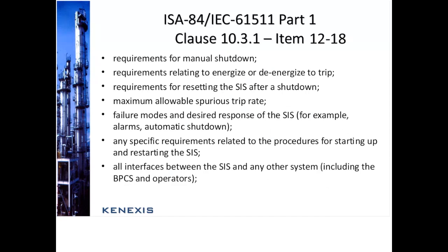Requirements for manual shutdown. Things like NFPA will require that even if you have a logic solver, sensors, and final elements, your valves, there needs to be a manual means by which a person can intervene and cause everything to go to the safe state without the use of the safety instrumented system. This could be as simple as a master control valve, or a master control relay in the burner management system.